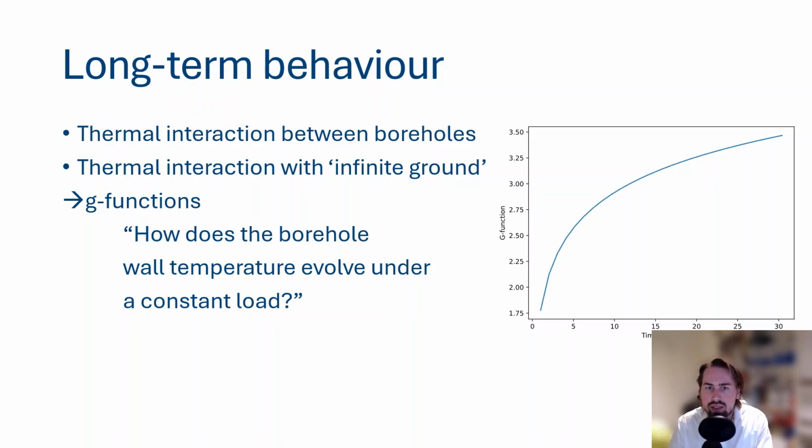So the longer we are injecting heat, the more the ground around the boreholes is activated, and the borehole wall heats up less and less. It will forever keep increasing in temperature, but always at a slower pace than before, because there is more ground that has been activated thermally. So that's the concept of this G function.